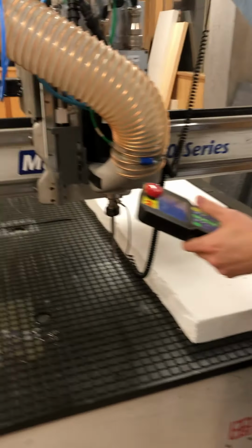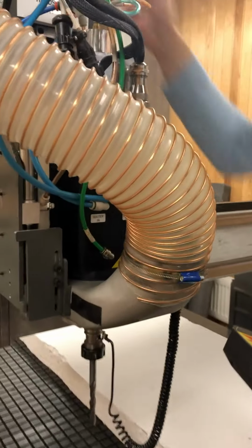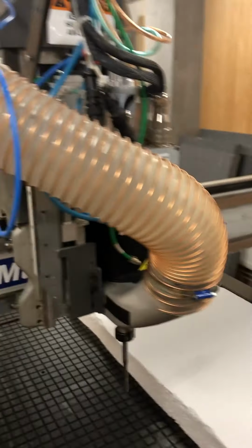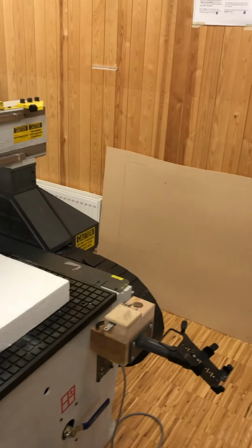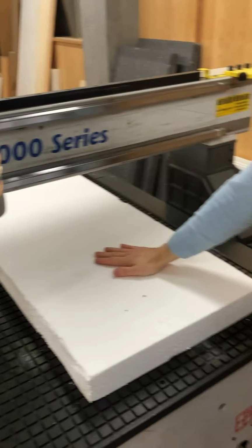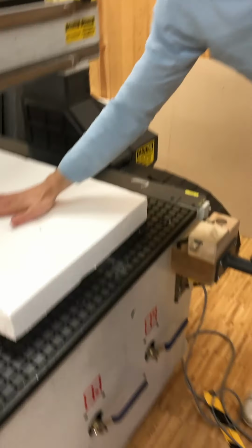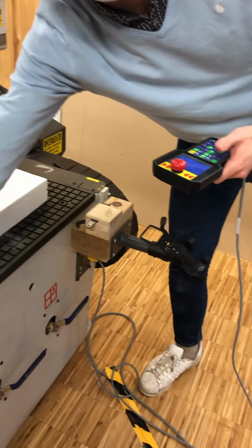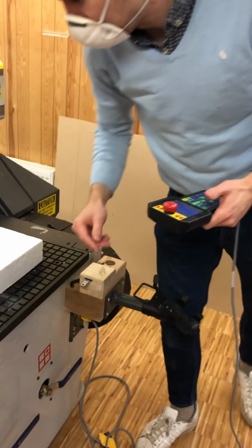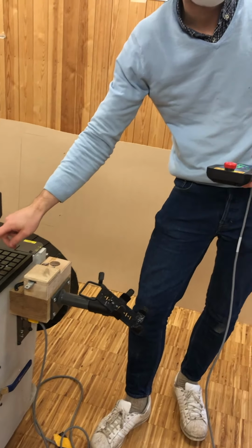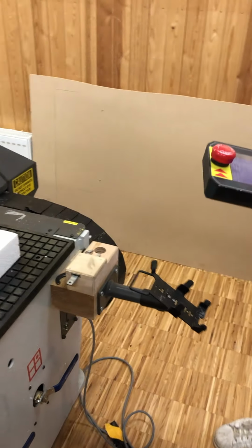Perfect. And then we need to remember to remove this. So let's remove this one, and this one. Alright. There's one thing left, I think. I hope so at least. Because now we have the surface depth, it knows where the edge of this end mill is supposed to meet here. It knows that it should not be cutting further down than here, but it does not know where this is. So we can jog.